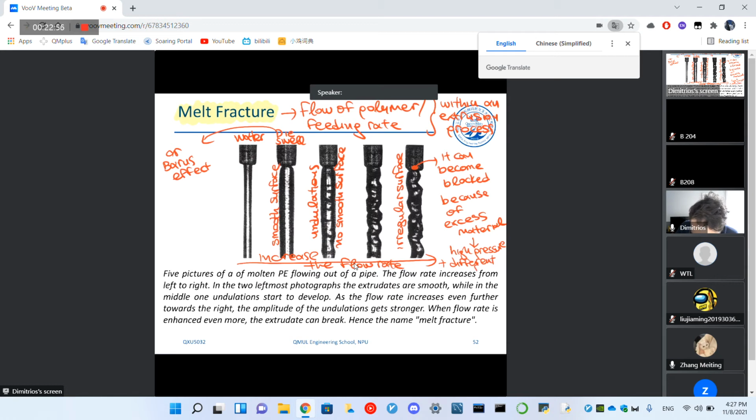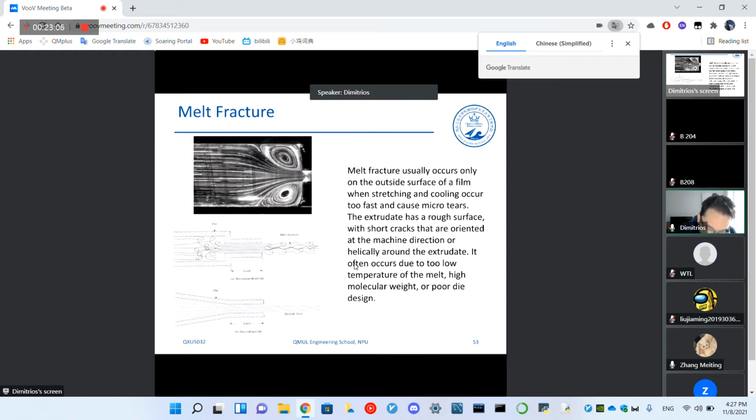And let's have a look at how a different flow looks in a melt fracture sample. You can see that we have two different types of flows. The first flow of the polymer comes out like that, but also there is an amount of polymer that essentially is trapped here at the edges. And because of that, we have this melt fracture phenomenon. That leads to melt fracture.